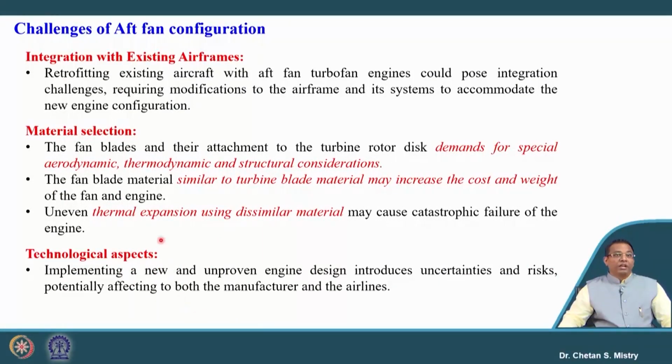If you look at the integration, as I was discussing, that is a big challenge. Then we have a challenge in terms of selection of the material, because the fan we are discussing requires special aerodynamic, thermodynamic and structural consideration. Since all my fan blades are placed on the LP turbine disc, if we use a similar kind of material, it will increase the cost of the material as well as the weight of the fan.